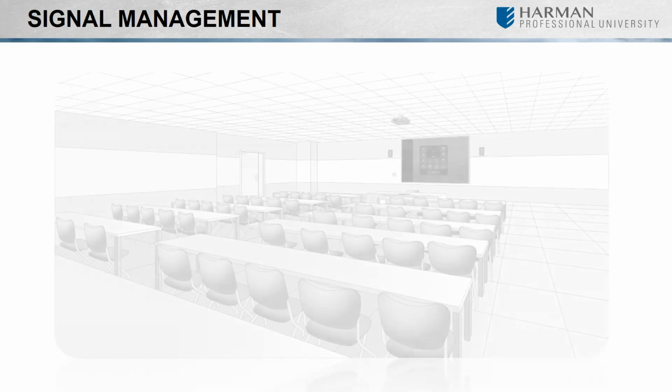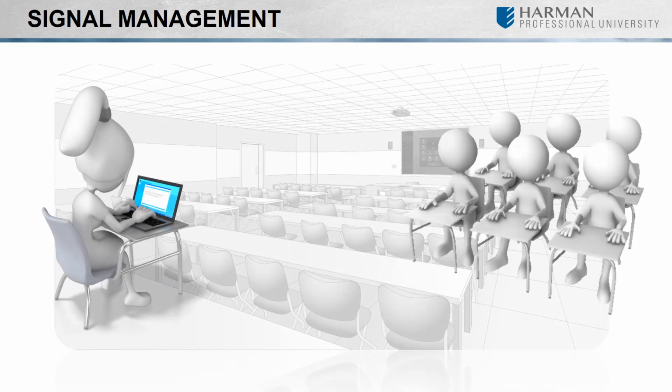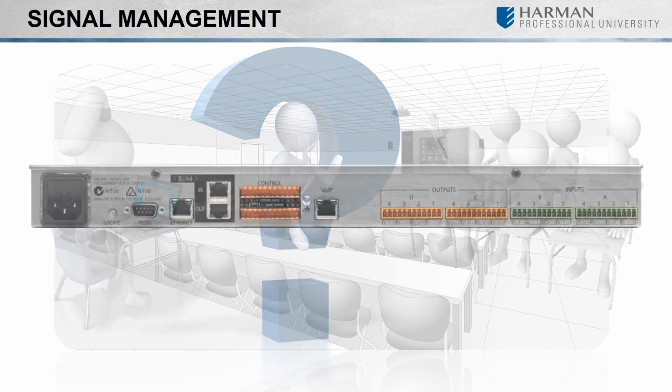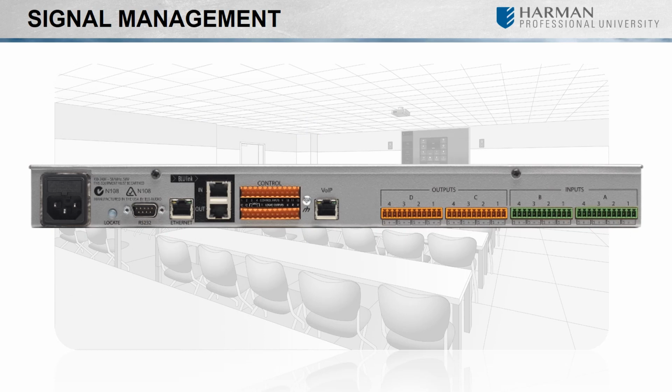Now let's consider distance learning as a requirement where a student may use a soft phone on their computer to call in. We'll need the ability to hear that student through local sound reinforcement in the classroom, and we also need the option to send our audio sources to that student. What should we use? The BSS Blue 103 is a great choice for this application as it offers 8 inputs, 8 outputs, 48 channels of BlueLink audio, and voice over IP.